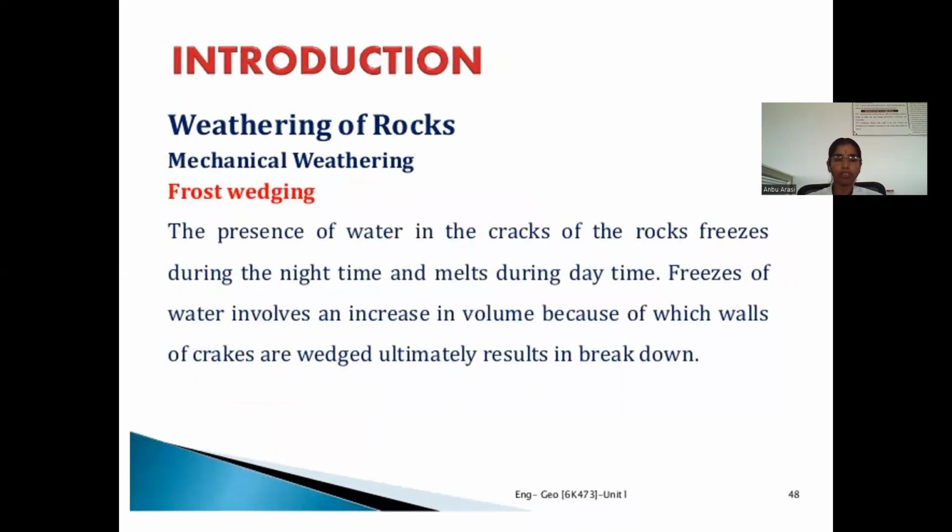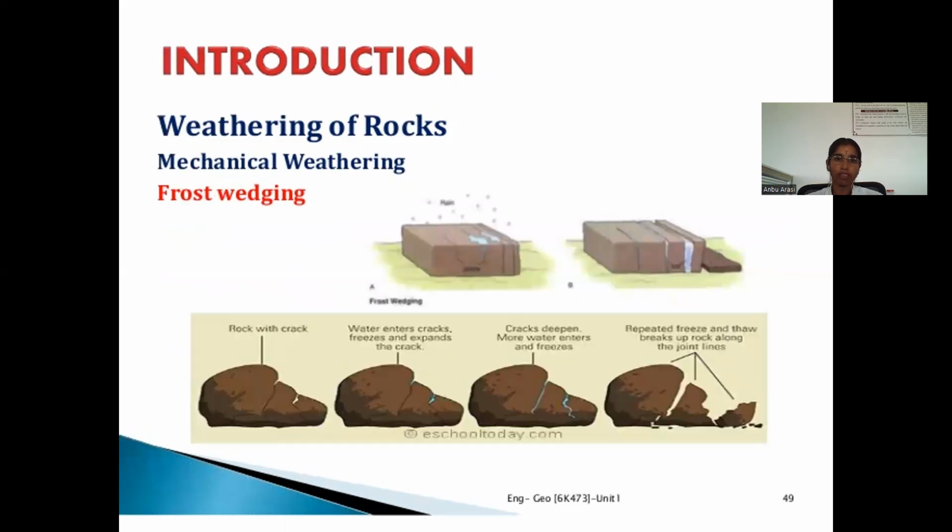Frost wedging. The water in the cracks of the rocks freezes during the night time and melts during the daytime. Freezing of water involves an increase in volume, because of which the walls of the cracks are wedged, ultimately resulting in breakdown. It is called frost wedging. This is the process of frost wedging.